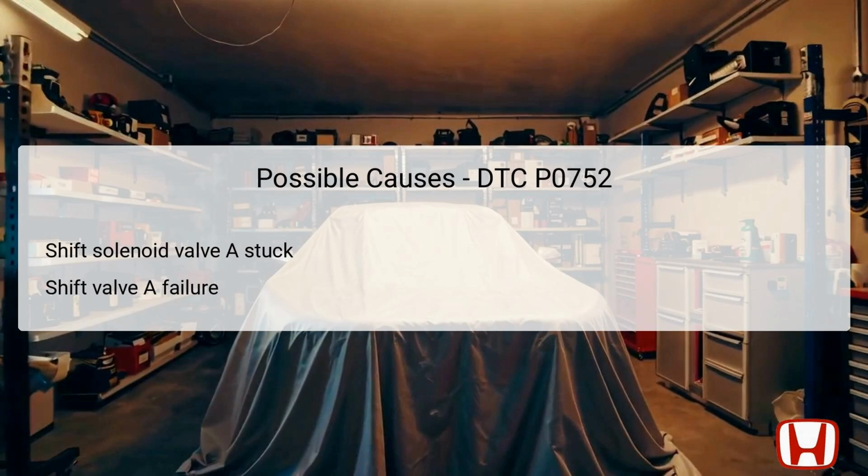The second possible cause is a failure of the shift valve A itself. If this internal component within the transmission becomes defective, it can also contribute to the same issues observed with a stuck solenoid. Both of these causes warrant diagnostic testing to ensure a complete understanding of the malfunction before proceeding with repairs. It's essential to confirm these conditions using appropriate diagnostic tools, like the Honda Diagnostic System, HDS, to verify component